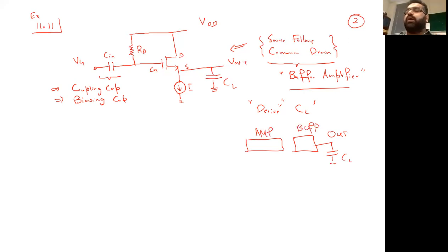So we get the characteristic so that our circuit doesn't get loaded, our output gain doesn't get reduced, and we can get the same configuration by the addition of a small buffer. Definitely some area constraints are going to come and you have to design a separate amplifier, but that's not the main goal of this intuition. The main thing is that they are saying we need to design a buffer amplifier or a source follower to achieve a high quality audio.